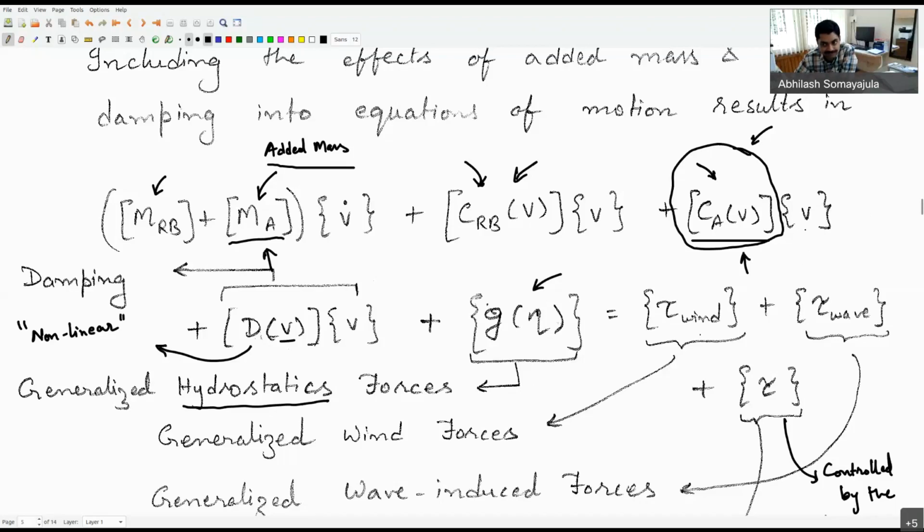The entire product should be in newtons. Not exactly, because the first 3 terms represent the force, the next 3 terms represent the moment, right? Yes. So the first 3 terms of the vector will be force, in newtons. The last 3 will be newton meters.